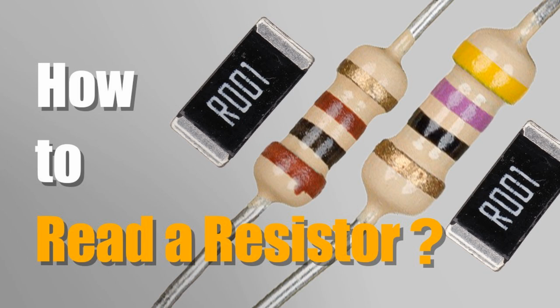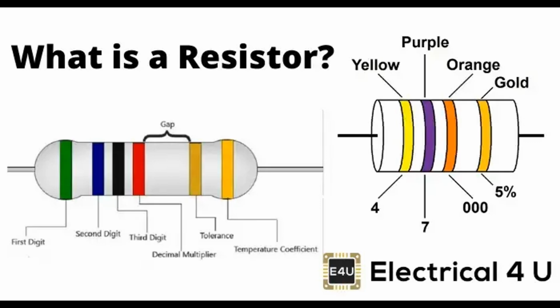Example: a high Q bandpass filter will allow a narrow range of frequencies to pass, useful in applications like tuning radio frequencies. Attenuation. The reduction in signal amplitude as it passes through the filter. Measured in decibels, dB, attenuation is a critical parameter in determining a filter's effectiveness at blocking unwanted frequencies.